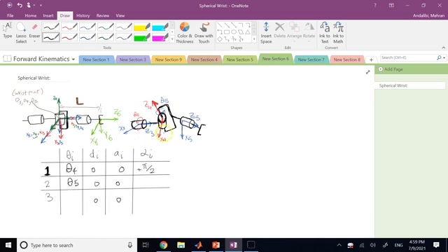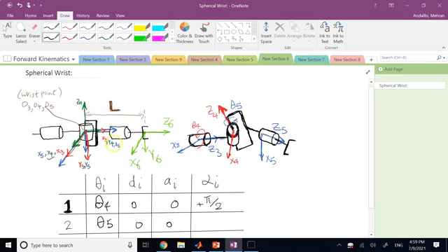And now that you got the x's aligned, what about the z's? Clearly, again, z4 and z5 are not aligned, as you can see here. And so now I have to rotate about the new x, which is x5 now. What should I rotate z4 to match with z5 along x5? Clearly, I have to go clockwise 90 degrees, and clockwise means negative. So there's going to be negative pi over 2 for this one, the twist angle.